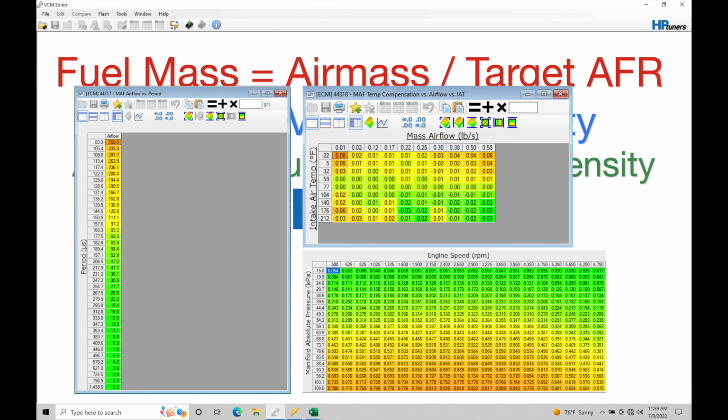Now, a lot of OEM manufacturers are redundant in their airflow modeling, meaning they have both a measurement of airflow and then an estimation of airflow. Now, we do this if we have a mass airflow sensor fail, we have a backup mode so we can run off of the MAP sensor. We also do the hybrid mode, or the OEMs choose to do the hybrid mode, because they need to have a backup air mass registration in order to characterize the airflow coming into the engine, the air mass coming into the engine under a transient condition.